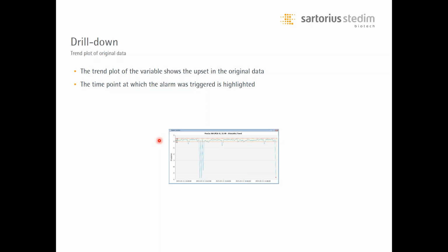So this is also how it becomes efficient. We go from that very top layer where you have multivariate monitoring of all these different units, and then you just click on whatever is showing you that you have an alarm. That drills you into the plot that's off, that drills you further into the contribution. You can click your way all the way into the particular process parameters that are out. And thereby we're actually monitoring all the variables at the same time, and whenever there's an alarm, even though we have this very sophisticated multivariate system running, we can get into a space that aligns very much with what operators are used to seeing.